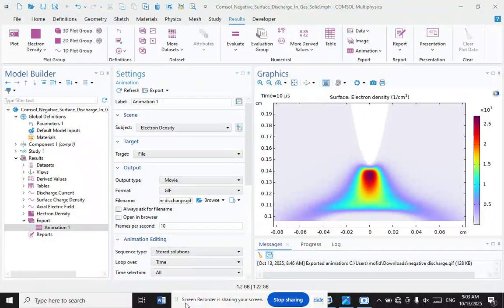The coating method is based on nanotechnology development and research to obtain superhydrophilic and hydrophobic thin films on the solar panel surface. Superhydrophilic coating reduces the dirt through a photocatalytic reaction, while superhydrophobic coating allows rolling water droplets to carry away the dirt from the surfaces. The effectiveness of this technique is not yet significant. Nevertheless, it could be combined with the previous techniques to ensure a more effective mixed technique.